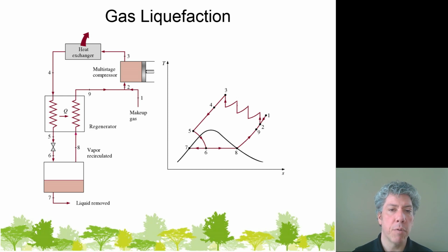So the move from state 4 to state 5, the way that gas loses heat is by gas that's going back to the compressor that's already very cold. Then from state 5 to state 6 we still have a high pressure but relatively low temperature gas. It would technically be above the critical point, so it wasn't really becoming a liquid.